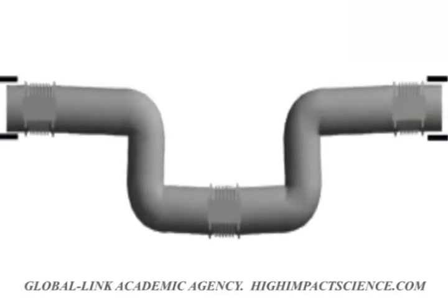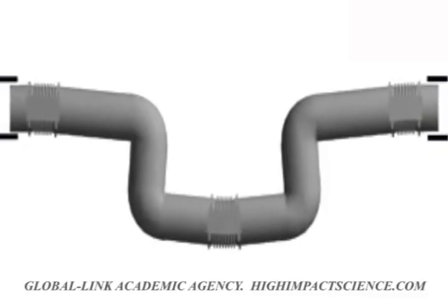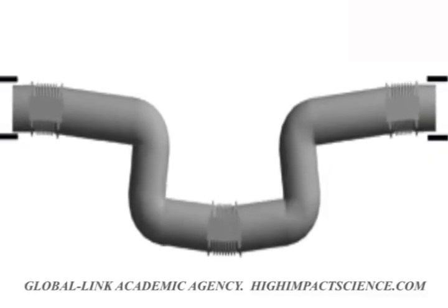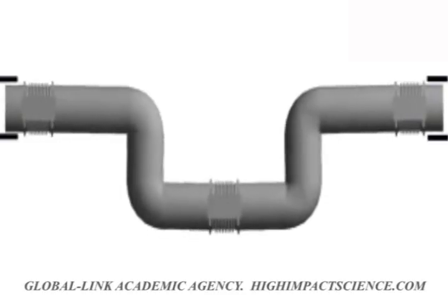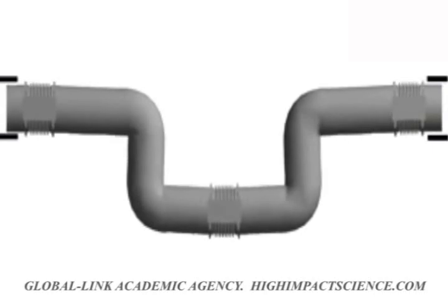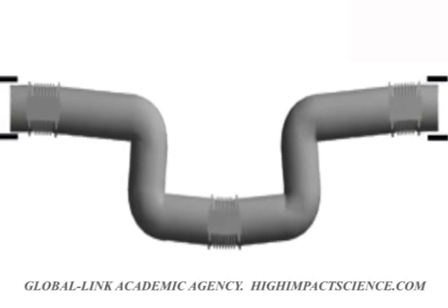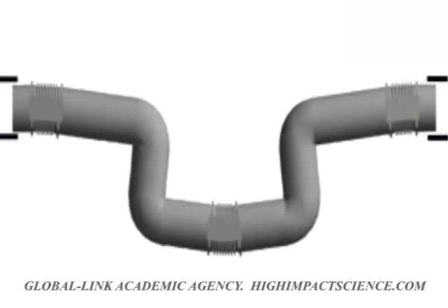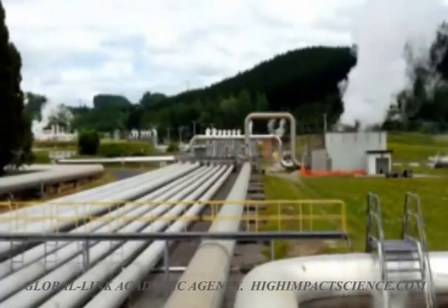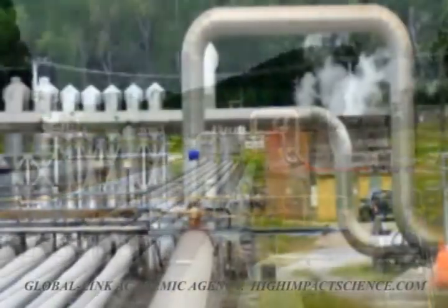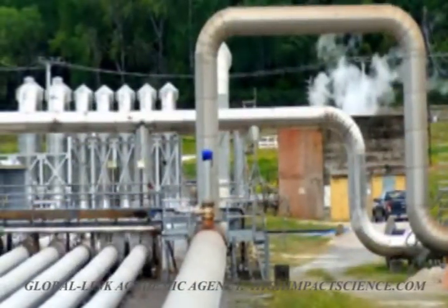Pipes carrying steam from boilers are fitted with loops or expansion joints. This allows the pipes to expand and contract easily when steam passes through and when it cools down. Without the loop, the force of expansion and contraction produced would cause breakage of the pipe. Use is made of this allowance when constructing oil and fuel pipelines.